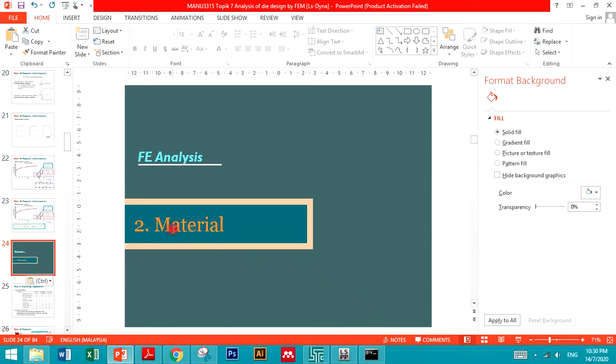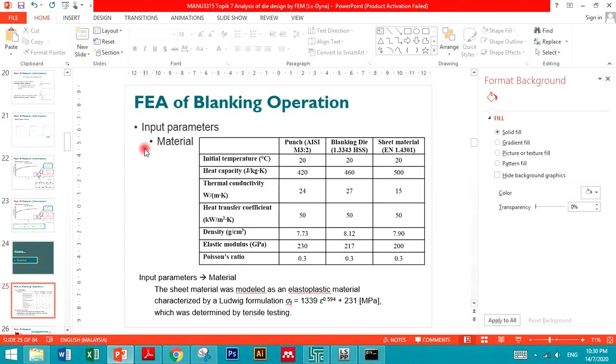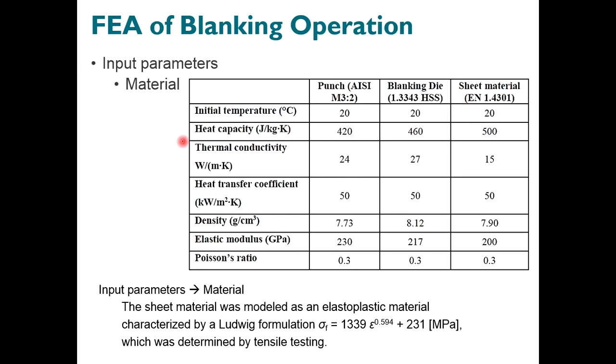Let's do finite element analysis. So now we will focus on the material input parameters to the LS-DYNA simulation. Here we will focus on the punch material, blanking, and sheet material. And here we have the temperature parameters, the elastic parameters, and the elastoplastic behavior by this Ludwig formulation.